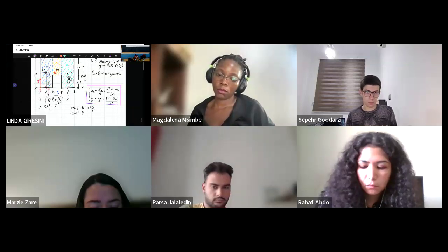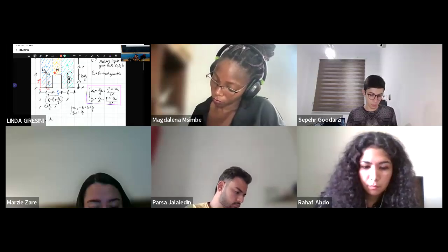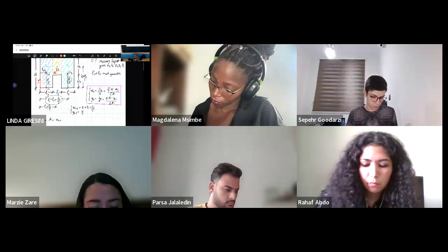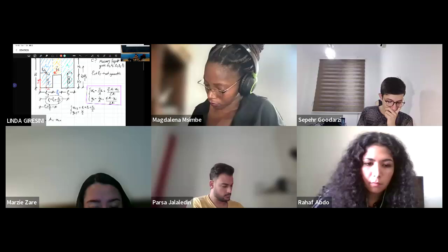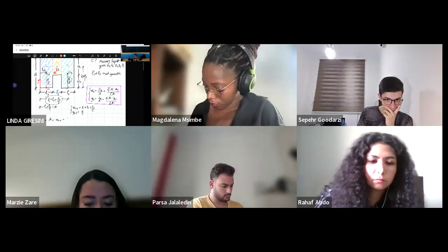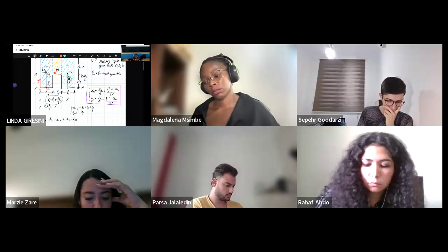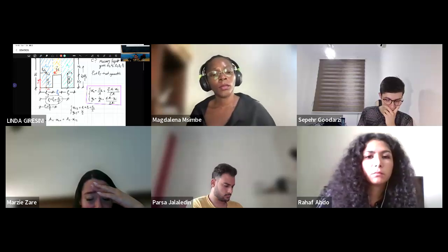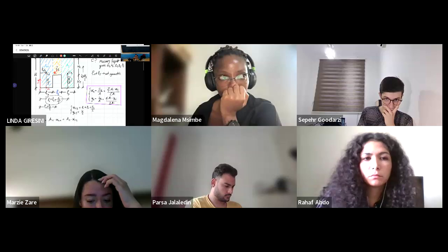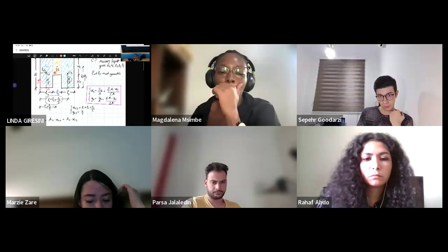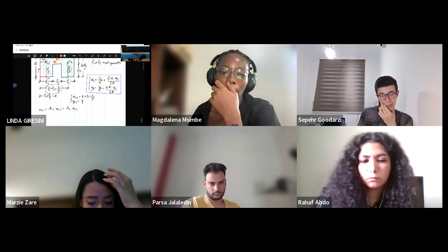So we have XC. XC is A1 times XC1, so the X coordinate of the centroid of the first area, plus A2 times XC2. So you have any rectangle area times the corresponding centroid, the distance from that axis. Divided by the sum of the Ai, this one. I just write it.